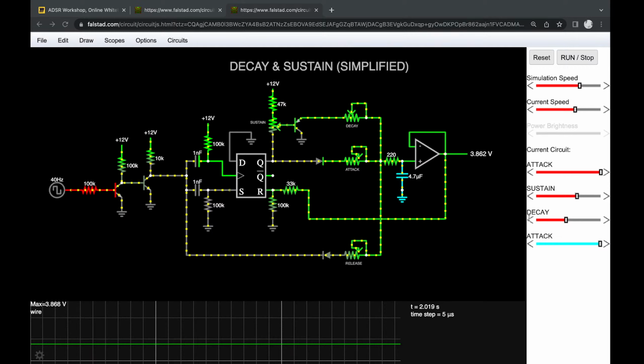Birek says, I built a triple VCO with saw, triangle, and sine output with your oscillator core. Shared an individual CV for the oscillators. All SMD, managed to fit it 70 millimeters wide. That sounds amazing, especially the sine output. I haven't worked on a sine output yet, so it's a mystery to me. But yeah, sounds really cool.